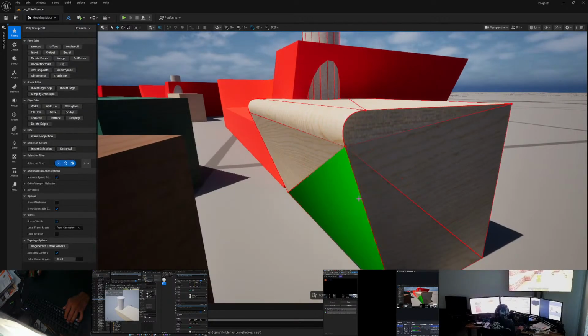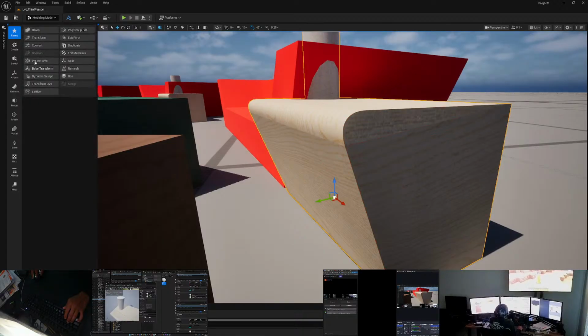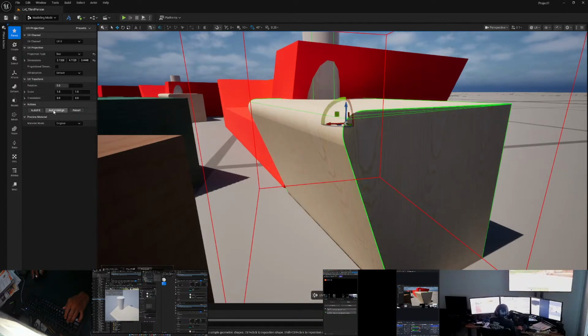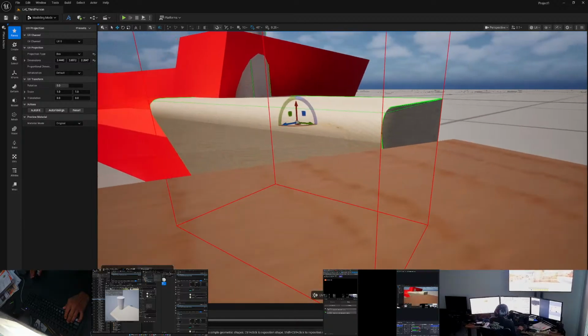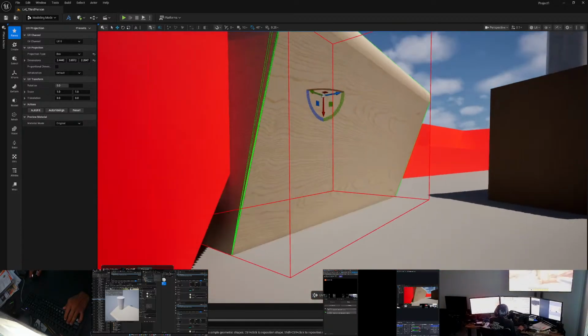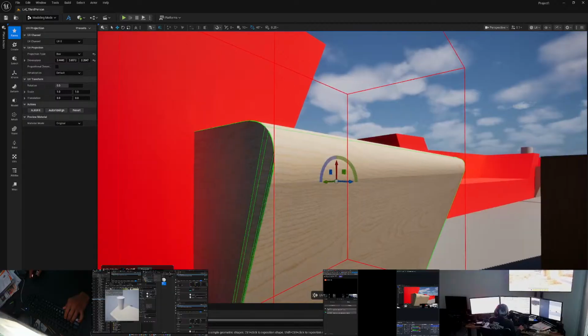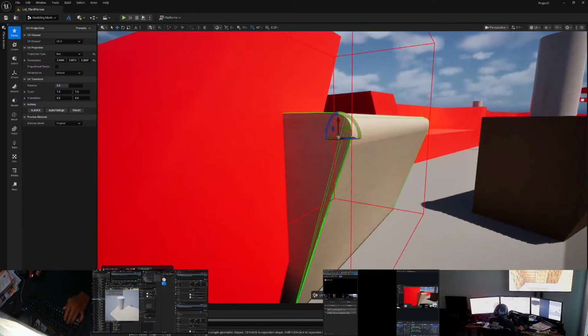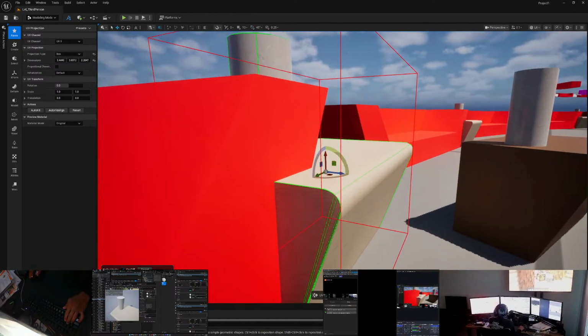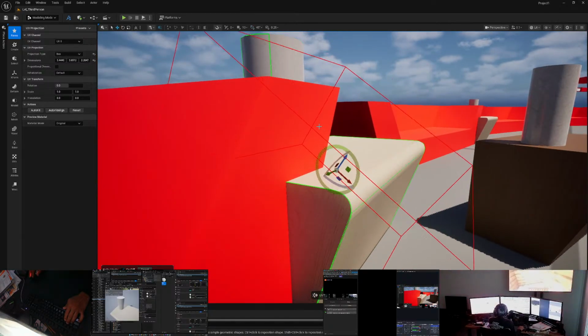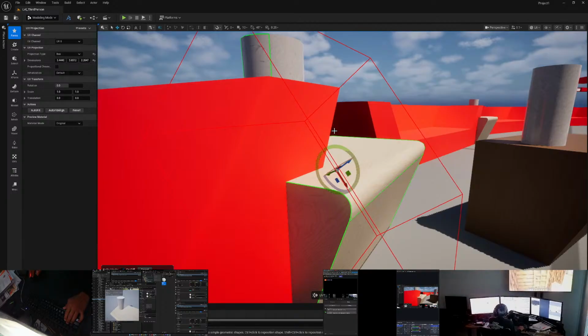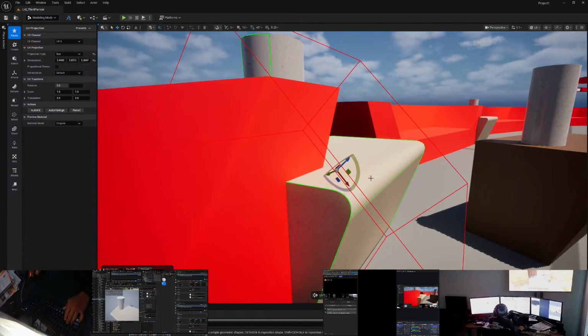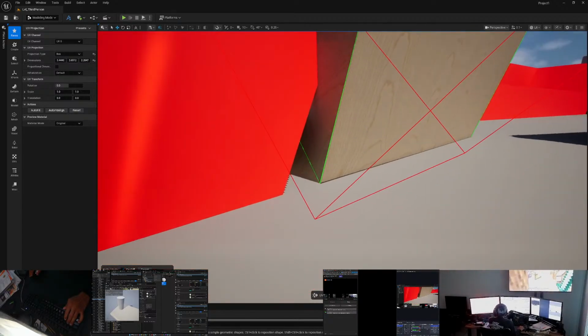Accept action. And then I can go back and accept the polygroup edit. Project UVs again. Auto align fit. And this will give me a much better aligned UV projection. Disable my rotation and see how I can modify this to look more appropriate, to where these lines aren't just absolutely breaking up on the sides.